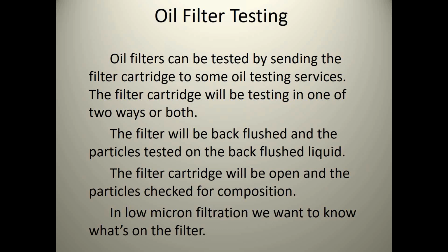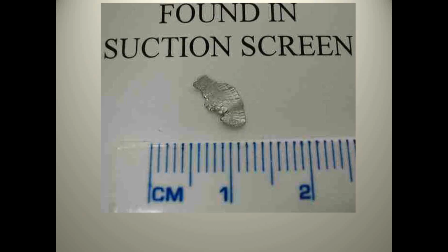But what this slide is trying to point out is that all those particles you filter out of your equipment are stuck on that filter somewhere. So if you want to see what they are or keep track of how much metal is in there, how much wear you have, it's in the filter.